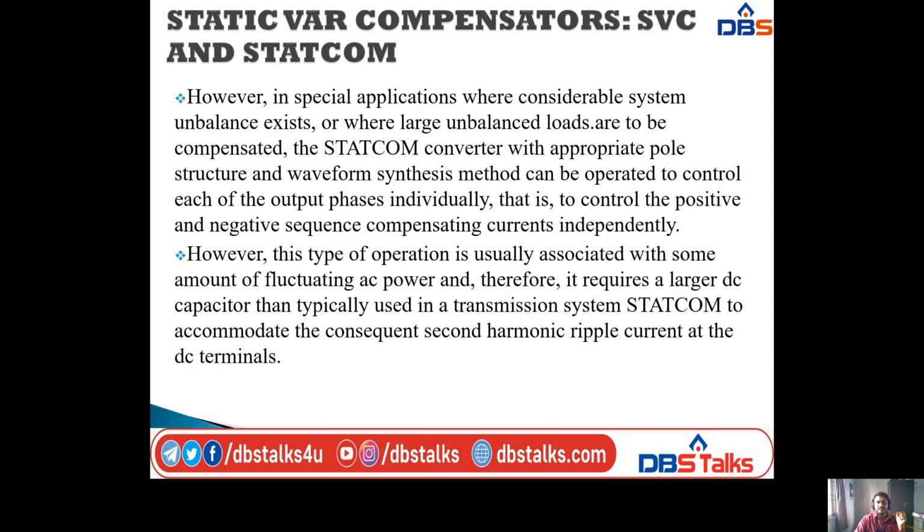However, in special applications where considerable system unbalance exists, or where large unbalanced loads are to be compensated, the STATCOM converter with appropriate pole structure and waveform synthesis method can be operated to control each of the output phases individually, that is, to control the positive and negative sequence compensating currents independently.